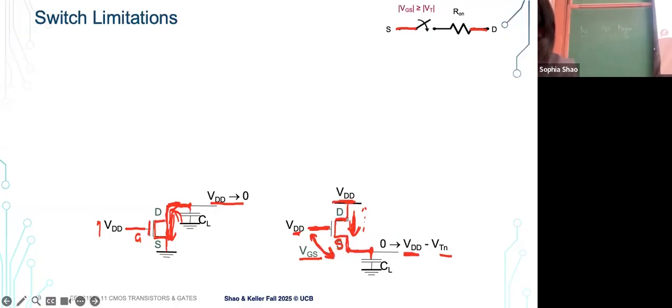The gate is VDD, which means the source node can only get to VDD minus VTH. So it cannot reach the perfect VDD, because of the threshold voltage difference between the gate terminal and the source terminal. Does it make sense?